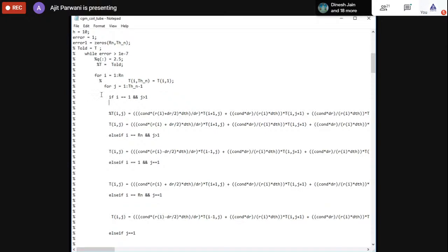Now, depending upon the boundary conditions, suppose it's a two-dimensional problem. In one direction there is a counter like I, in another direction a counter like J. Like I told you, APTP is equal to AT plus AWTW. For similar grid points, like from 1 to 10, when I described the Gauss-Seidel method, I told you that you will get equations that are all of the same nature.